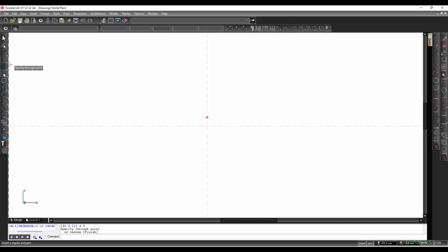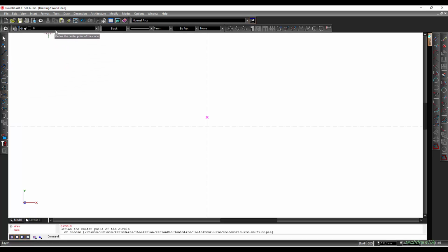Therefore, I'm going to select the circle tool. So I'm going to select that over here, and then immediately I want to place it on the correct constructions layer. The circle is just the start of the construction that I want to use for determining the octagon. So on the constructions layer, I select that. Now I can see that my constructions layer is active. I'm going to zoom in, and I'm going to make sure my snap is going to snap to that intersection.